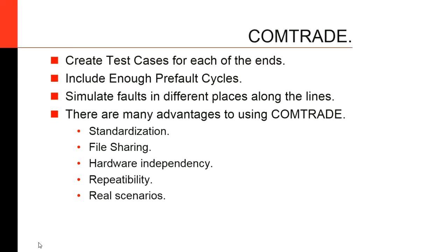It's a standard that allows a common representation of oscillography coming from any kind of oscillographic recorder in the system. And since it is a standard, it allows people to see it in standard tools, some of them free on the internet, or built into the configuration tools used to configure relays.